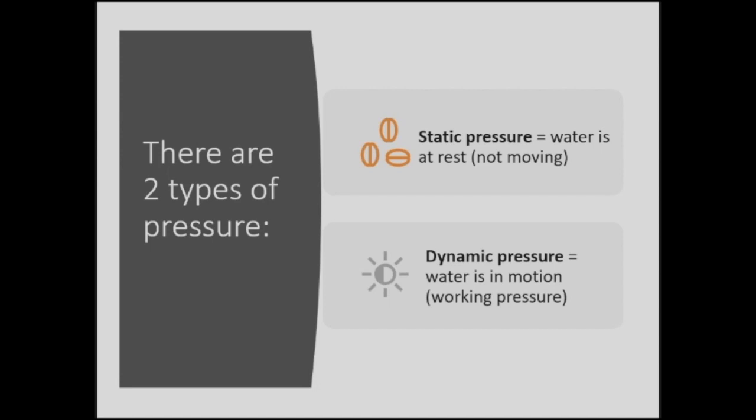What about dynamic pressure? How can the pressure change whenever the system's working? We just said two of them. So, elevation can change it, pump can change it. What else? Pipe distance, right? Size, opening maybe, velocity of the system. Charles is going to talk a little bit about that in a minute, but how maybe rough our pipe is. Somebody said how short it is. That's going to change dynamic pressure. But the length of the pipe's not going to change static pressure. The only thing that can change static is elevation and the pump, right?